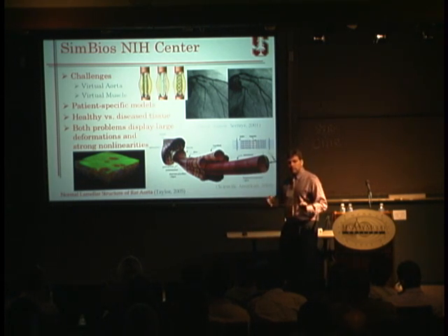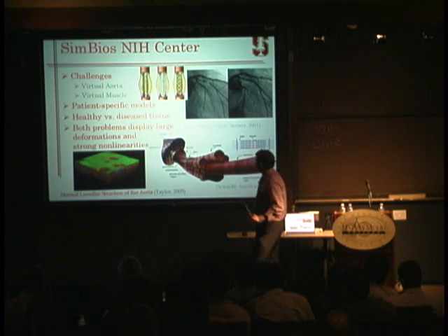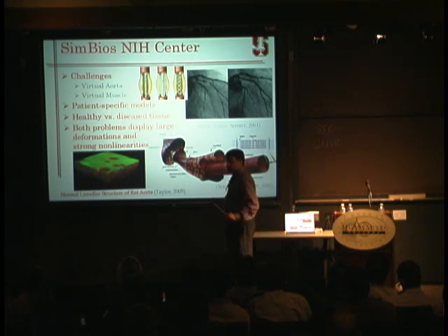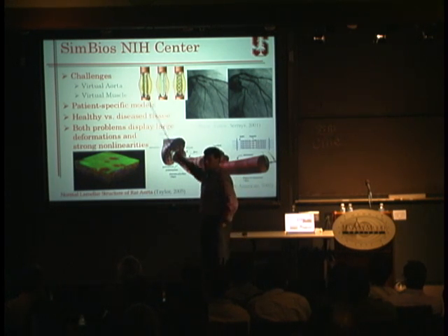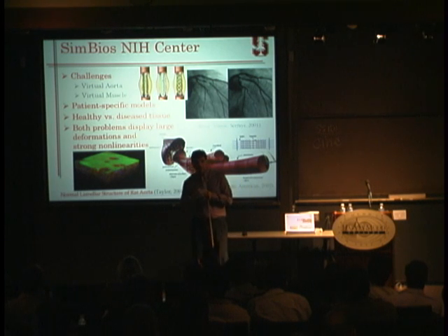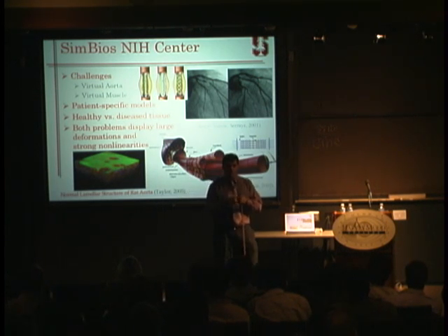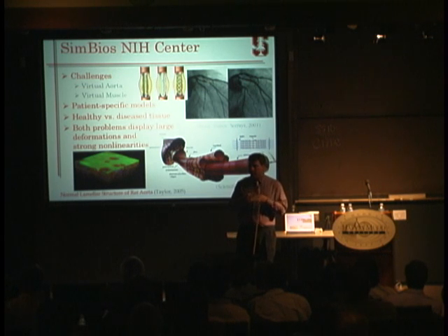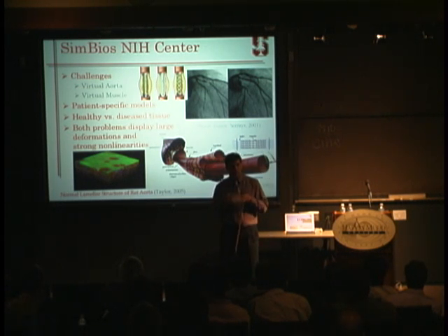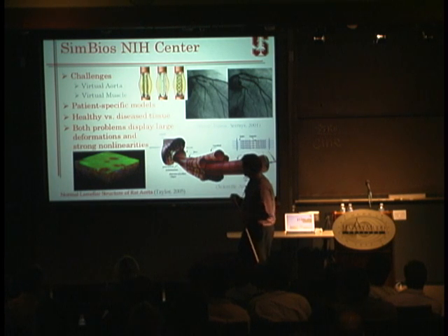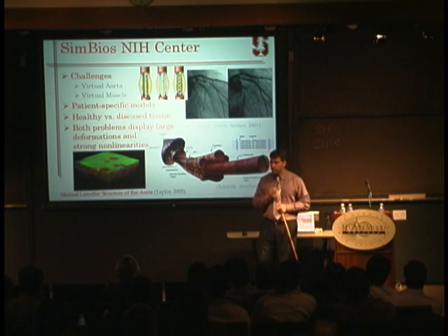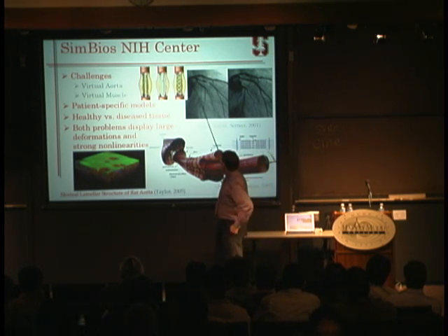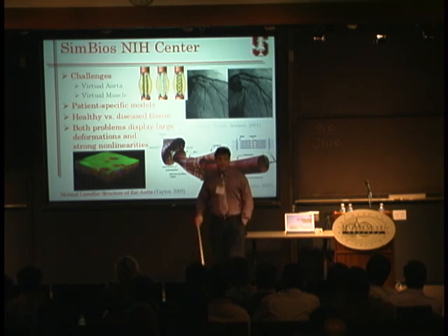This type of model would be used eventually, for instance, for the simulation or the study of a procedure of stent implantation on an occluded artery. In this procedure, you insert a stent into the artery where the occlusion is, you inflate it with a balloon, you compress the plaque or the calcified tissue that is occluding your circulation, and you leave the stent there that will prevent the artery from compressing back again. In doing that, you deform an initially very compressed artery into a largely deformed shape.